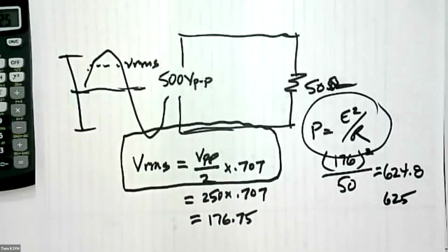I know that sounds ridiculous, but that's the case. All power is RMS power all the time. It's just the power at the peak of your voice, the power at the peak of your signal, but it's still the RMS power at the peak. Power is RMS always.